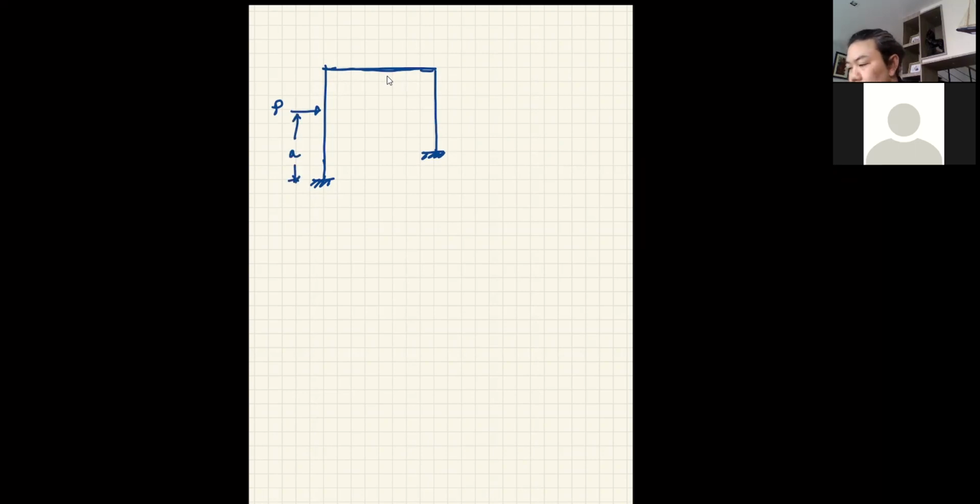Okay, now we know because of the assumption that the sway is going to be equal, so the delta is going to be equal. Notice that now the point is this is going to be equal, but because these two legs are not equal anymore, that would mean you are going to have different psi terms.